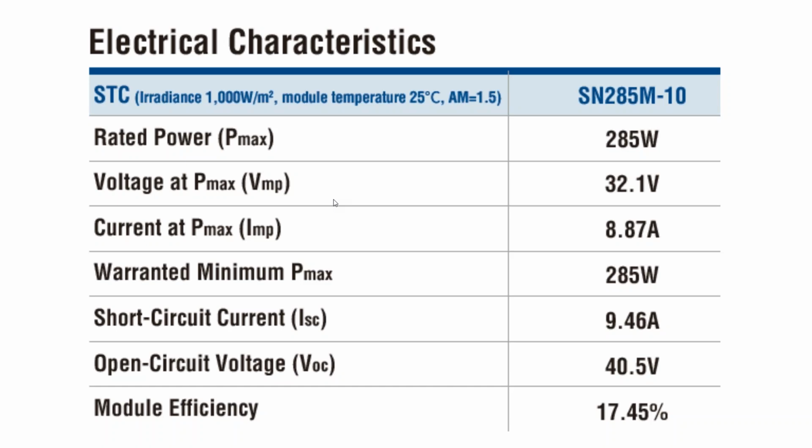And so every solar module is given this standard test condition to make things standardized, but it's not really indicative of field performance. In the past, there have been other ratings to indicate field performance, but you can really just look at the spec sheet and look at the temperature coefficients of power to see which panels are going to perform better at higher heat, for example.